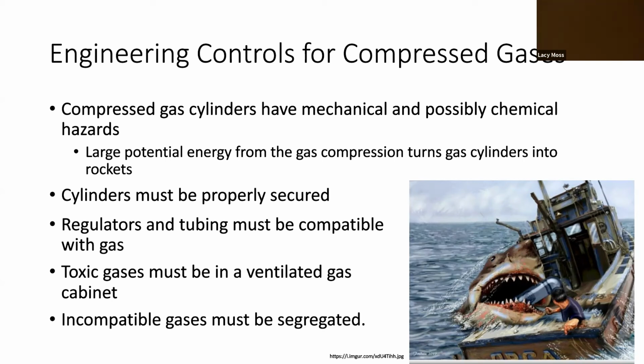You always want to make sure that you're using the correct regulator and tubing for the gas cylinder that you're using. And if it's a toxic gas, you want to make sure you're in a well-ventilated area. And incompatible gases must be segregated.